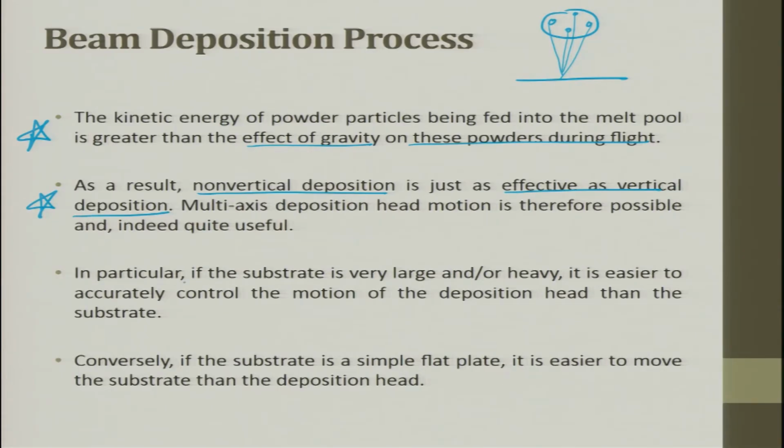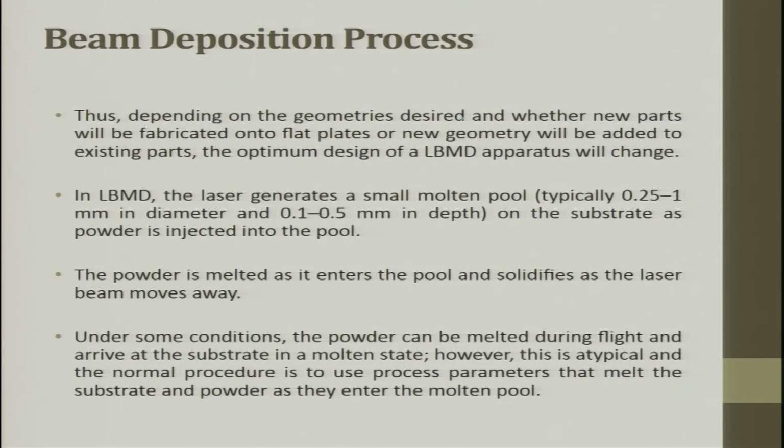In particular, if the substrate is very large and or very heavy, it is easier to accurately control the motion of the deposition head than the substrate. Conversely, if the substrate is a simple flat plate, it is easier to move the substrate than the deposition head. Thus, depending on the geometry desired and whether new parts will be fabricated onto the flat plate or new geometries will be added to the existing part, the optimum design of the LBMD apparatus will change. Design of the machine will change.